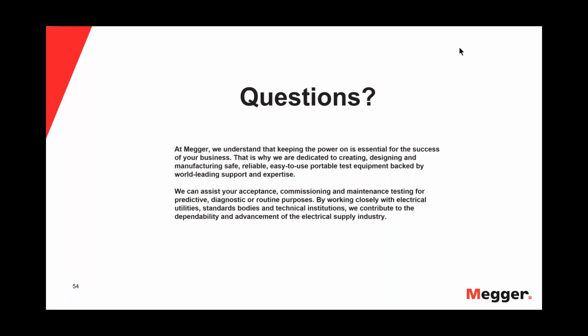Overall, from a practical point of view, it's more important that you understand, okay, on longer cables, I need a wider pulse because I need more sending energy. I need to send more energy into the cable. You need a higher magnitude, better signal to noise ratio, and also more energy. And another thing, completely independent of that, is the sampling of the TDR. That also has a frequency, like the microprocessor that works in modern day TDRs, that has a true sampling rate. And that is typically also very high in the megahertz, let's say topping off at 400 megahertz, for example.